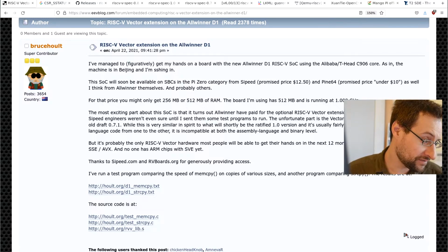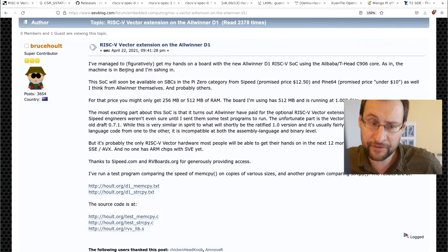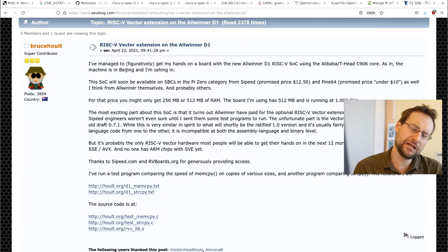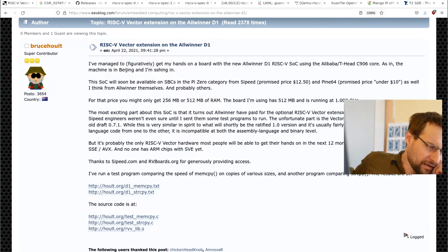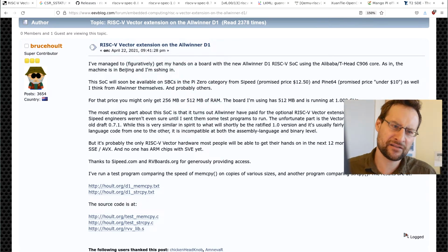That is amazing. Okay, you don't have task switching. Fair enough. So you only enable the floating point bits, basically the changed bits that I just outlined. Then you need to be careful, obviously, not to clobber your floating point state. Did you find any other things not working?